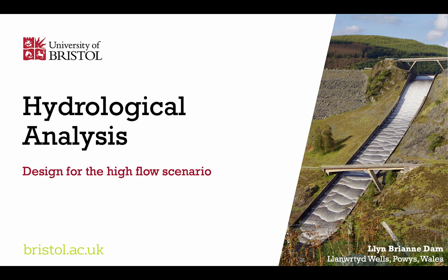The next set of hydrological analyses you need to do are to design for the high flow scenario. So this would be the scenario where there's a large storm in your dam catchment and this generates a lot of water which then flows into the reservoir, and you have to make sure that you've got sufficient excess storage capacity to receive that water and route it through and over the spillway.